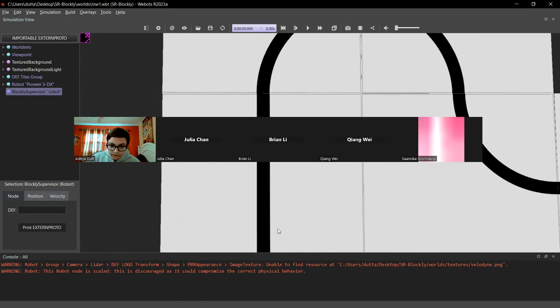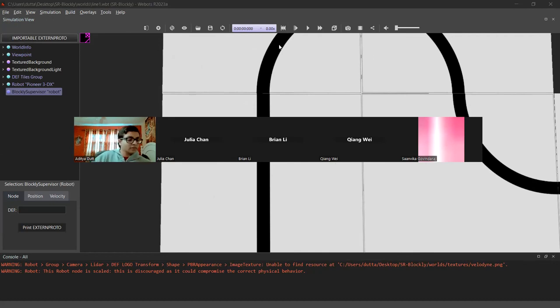The way this works is, if we have a robot on a black line and we have our sensor here, right now the sensor is seeing a black line. With one-eye line tracing, it's very simple: if the robot sees this line, have the left motor go forward at some speed and have the right motor stop.